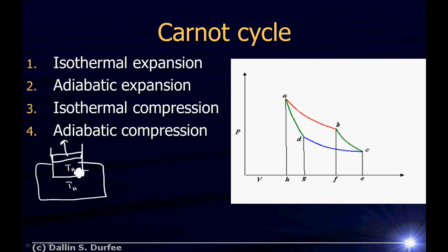If you played that backwards, you would see this piston going down, it's at temperature T hot, and heat is flowing out. That's exactly possible, right? That's not weird. You'd say there's nothing more weird about heat flowing out at constant temperature than heat flowing in. So an isothermal expansion at constant temperature can, in theory at least, be done reversibly. An isothermal compression, same thing.